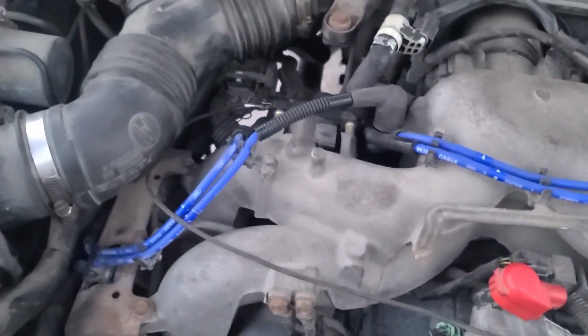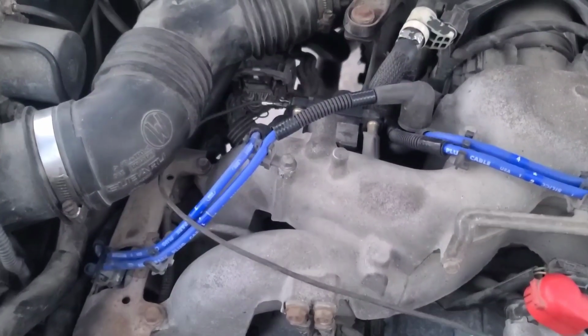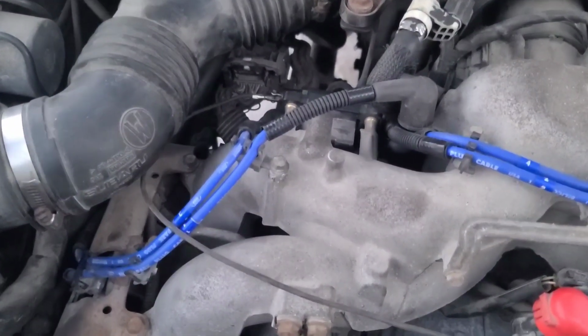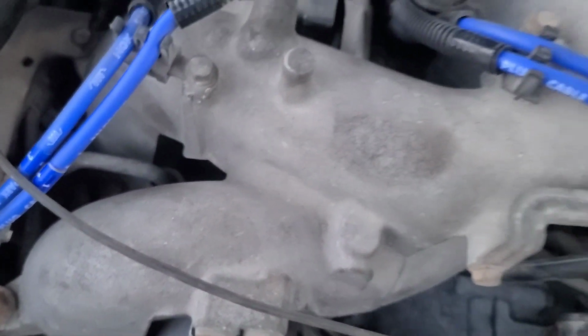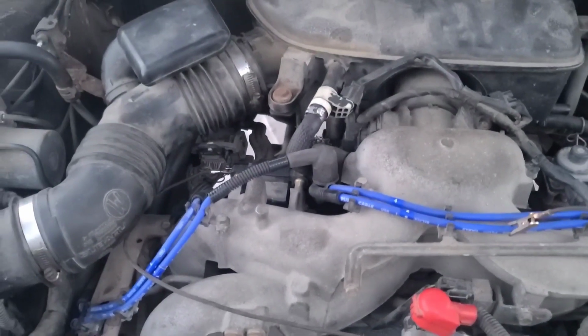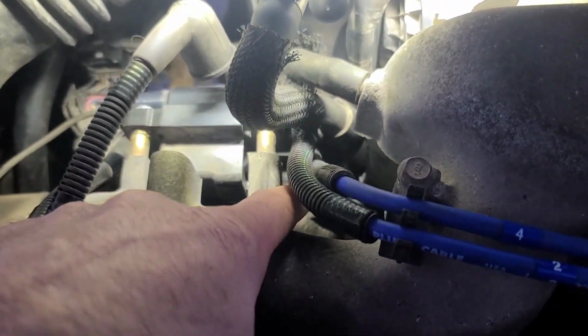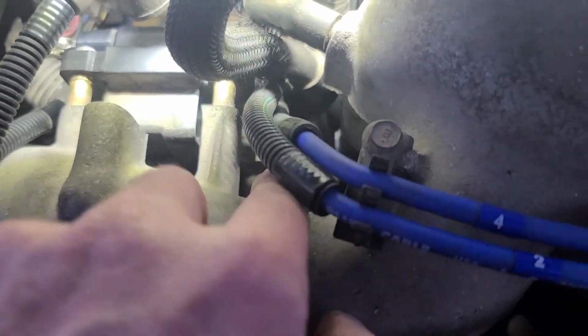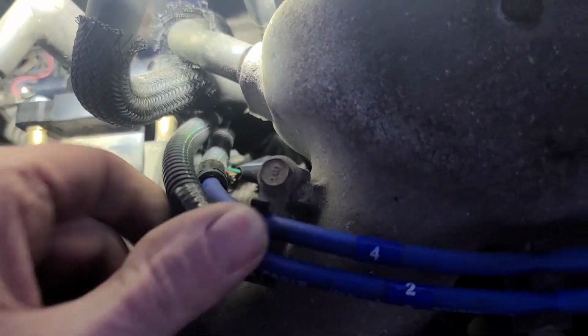It's a wasted spark system. I really need to check the control side of the coil to see if we're getting a pulse on there. And then we also have the injectors. I've got to get a trouble light out here now. It's starting to get dark. So the control side of the coil is way down inside there, and I can't get at it very conveniently. It looks like the connector's plugged in. Maybe if I move these plug wires out of the way.